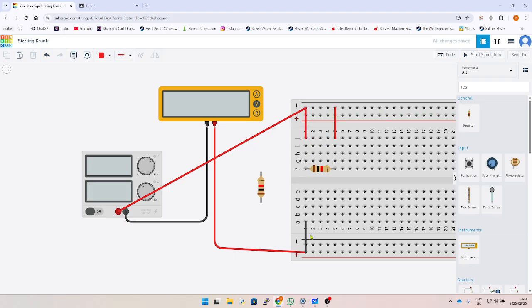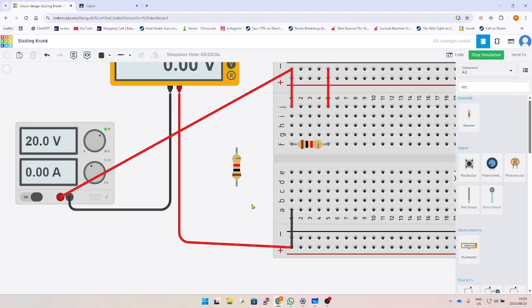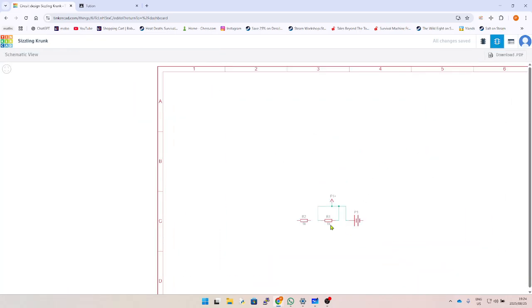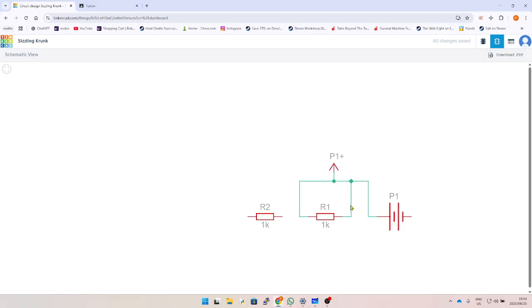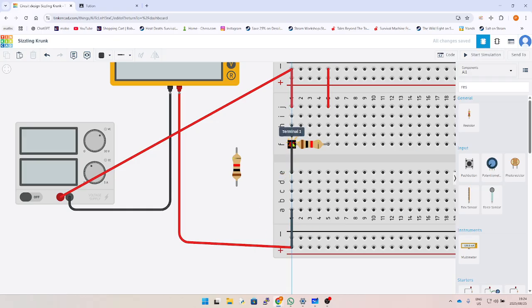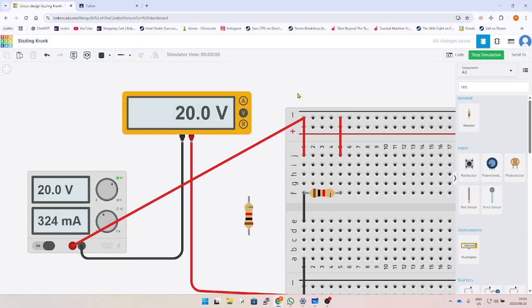The correct way to do it is you have to power it like this here. So let's see what happens if I press start. The voltage meter reads 0. Because why? Look at the circuit here. I'm connecting the positive terminal to here obviously, but is this side connected to anything else? No. Meaning the circuit is broken. Here's the resistor. It's making a complete circuit, yes, but the actual power source is not completed. Meaning if I connect it like this here, the circuit should in theory work.